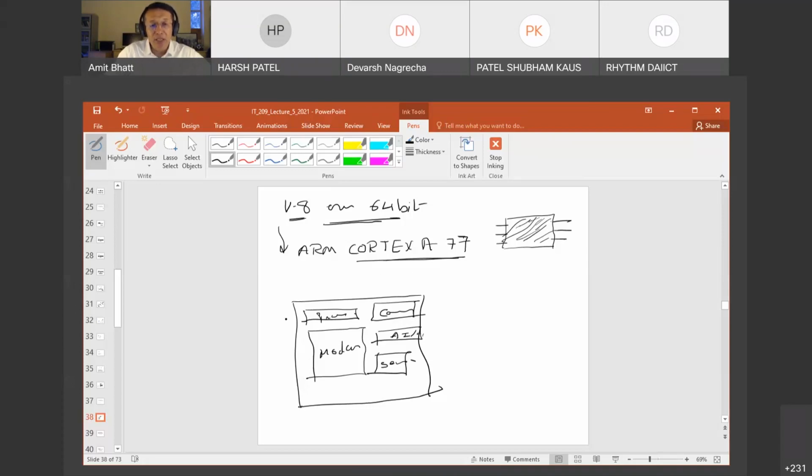So what people would do is, say MediaTek would buy a processor from ARM, and ARM would give them this design saying that we have already laid it out. We have already written the RTL code. We have laid it out and created a file. We will just give you input and output details. And of course, certain timing details: how long it would take for an input put in here to come out on the other end as an output. How long will it take? That information would also be given. So those companies would put it in here and then connect it with other things.